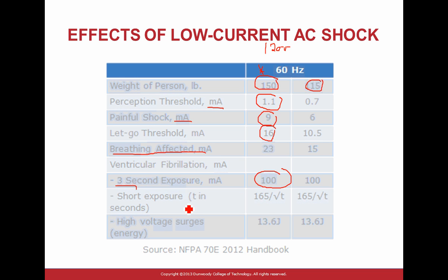So these are a few things, guys, that you can see. It doesn't take much to really freeze you in place. Look at that, 16 milliamps, or what it takes to freeze your muscles, and cannot let go in a circuit, on a say 120 or 240 circuit. So that's why your GFCI trips at 5 to 6 milliamps, right? That's enough to let go. But you go higher than that, it will burn you.